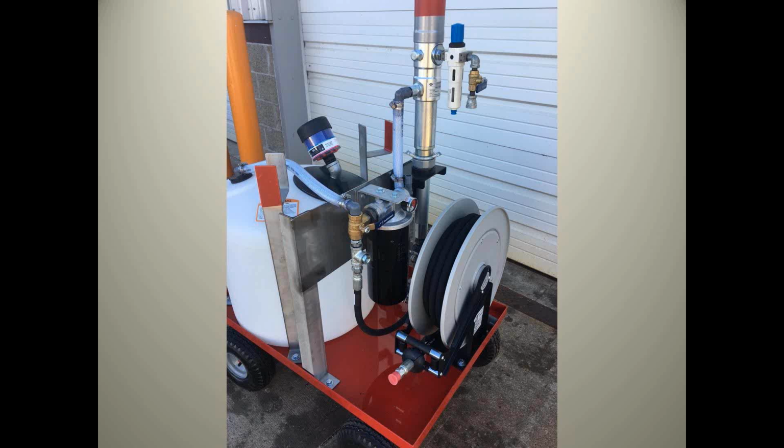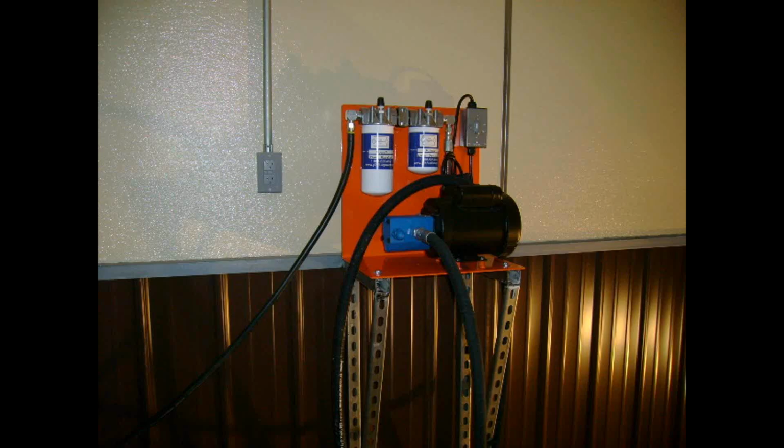This is a little lube trailer we built for a number of our customers. We've sold about 50 of these now. It's a little four-wheel trailer you can pull around your plant, which has a little tank on it with 22 gallons of oil. You can filter the oil in the tank, or filter oil into the tank. You can go up to a component and kidney loop it with this air pump and clean up a hydraulic system. You can use the hose reel to top off hydraulic systems and gearboxes. So lots of little uses for a little four-wheel cart that can be taken around the plant.